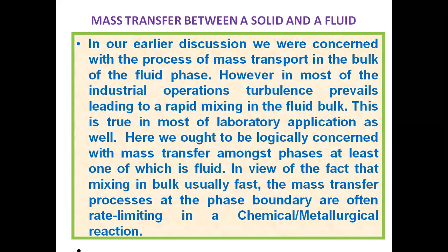Let us, for the time being, take the example of the carbonization process, formation of coke. Is there not mass transfer? It is mass transfer. Once we are heating a particular coal, either in nitrogen atmosphere, or inert atmosphere, or in vacuum, what are we doing? If it is an inert atmosphere, we are heating it. The role of the inert atmosphere is not to allow the oxidizing atmosphere into the system. That's all. But once you are providing heat, from the lattice of this particular coal, the organic matters, generally volatile matters, escape out. There is mass transfer. Suppose we are taking X gram of coal. After carbonization, we take it out. It will not be X gram, it will be less than X gram. If it is Y gram, then X minus Y escapes out. That escape is mass transfer from the system to the outside.